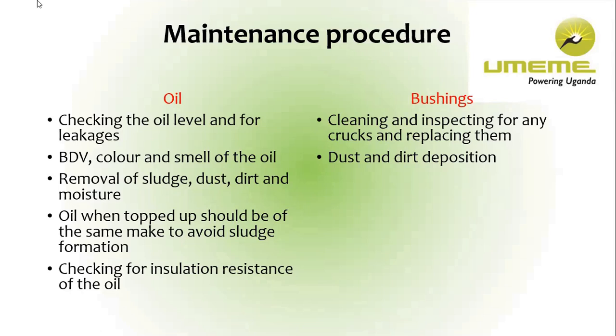And when the insulating properties are reduced, there's a likelihood that the cellulose, paper-like insulators on the windings can become oxidized by the water that has entered, and that will automatically lead to shorting of the windings.